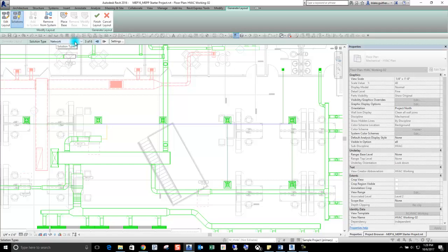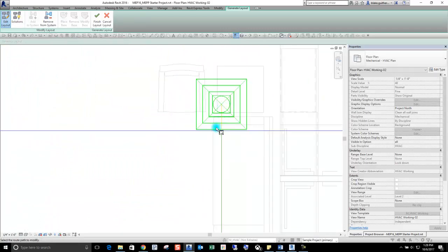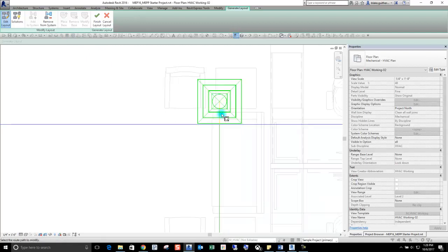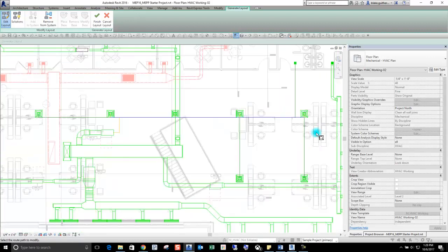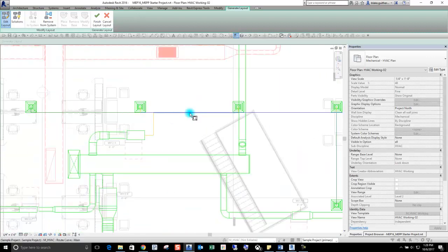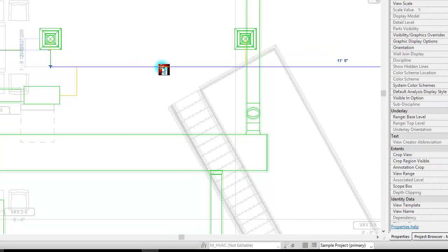All right, so let's edit the solution. So when you see yellow lines like this, that's Revit telling you that with the fittings you've chosen in your settings, it can't make this connection work. So it'll end up breaking it. There'll be an open area there in the duct. To fix some of these, you just pick your duct and you stretch it down.